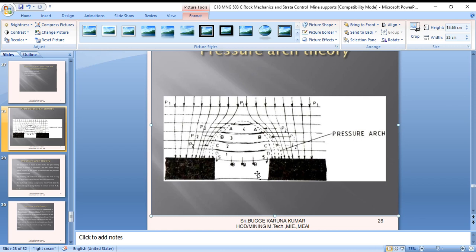In many coal mines, there is no self-supporting roof member within a reasonable distance above the roof line from which the roof bolts can be anchored to suspend the incompetent immediate roof. The successful applications of roof bolting in these areas suggest a reinforcing mechanism other than suspension.